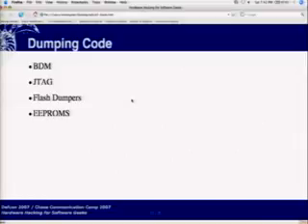Some BDM systems also let you do things like clock stepping to slow down the process and inspect each register as each clock cycle passes, modifying registers and memory locations. These actually have a BDM port on the back. As you see, I put a pin header on it. It's actually a one-wire bus that allows you to debug the chip.